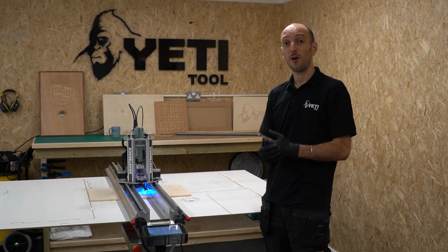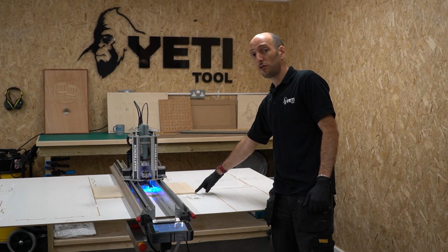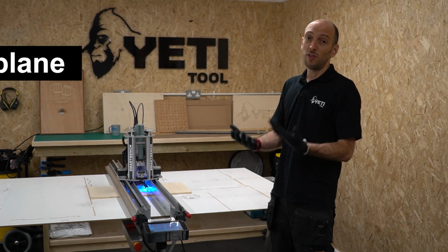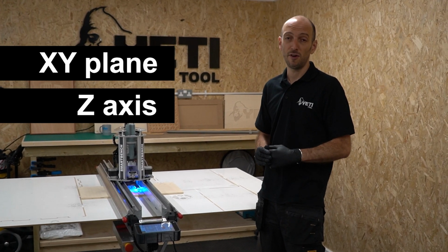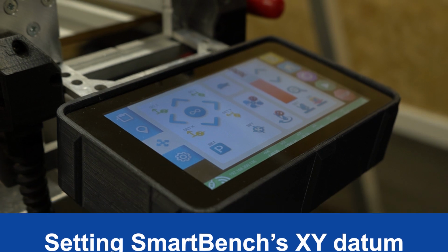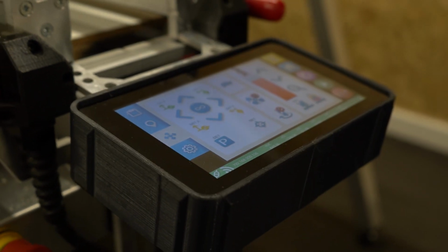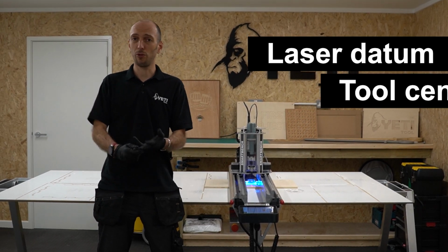So, you remember from our job file that we've set our job file datum to be in the bottom left corner on the top surface of our stock. So our next job is to tell SmartBench that that's where its working datum needs to be. We do this in the XY plane and then the Z axis. So we'll look at setting it in the XY plane first. We're going to do all of our movements in the Pro app. And we'll be using these buttons here to navigate the Z head around to be able to set our XY datum. And we've got a couple of options. We can either use the laser datum or the tool center.